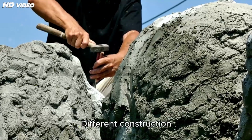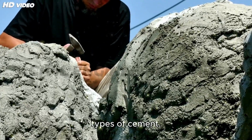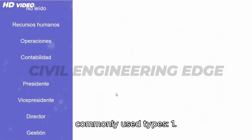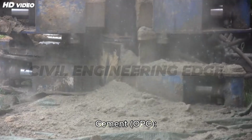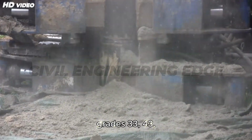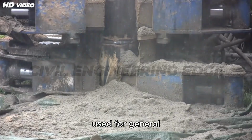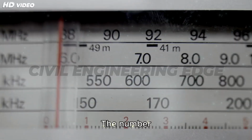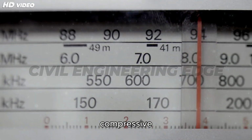5. Types of cement. Different construction needs require different types of cement. Here are the most commonly used types. 1. Ordinary Portland cement (OPC). Available in grades 33, 43, and 53, OPC is used for general construction. The number represents compressive strength after 28 days in MPa.